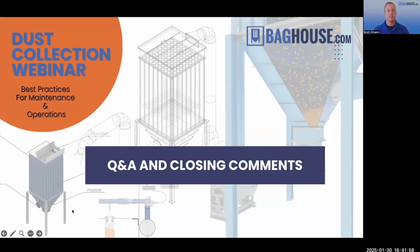Yeah, good explanation. And like we said too, sadly, there's a lot of facilities where people have never even seen that, right? Because for whatever reason, their filters are always getting holes and stuff like that. So they've never even experienced it at the end of their life. Some of the larger applications where they have big reverse air baghouses, they're able to plan this out months, even years in advance because they're carefully watching the differential pressure. They have it all trended. And they even monitor the emissions coming out, and they can predict pretty accurately on those kinds of systems months and years when they're going to fail. And that's how they can schedule those change outs at a convenient time.